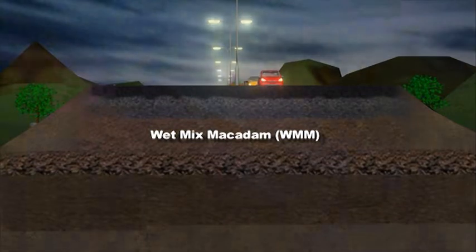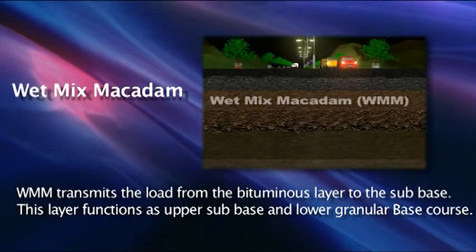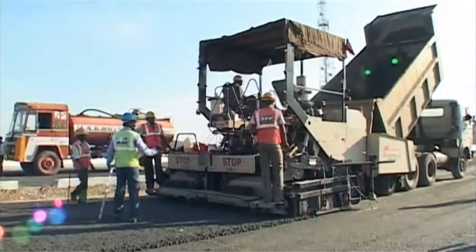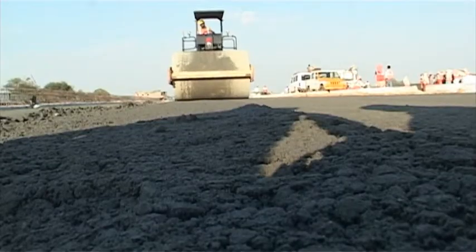Wet mix macadam. WMM transmits the load from the bituminous layer to the subbase. This layer functions as upper subbase and lower granular base course.